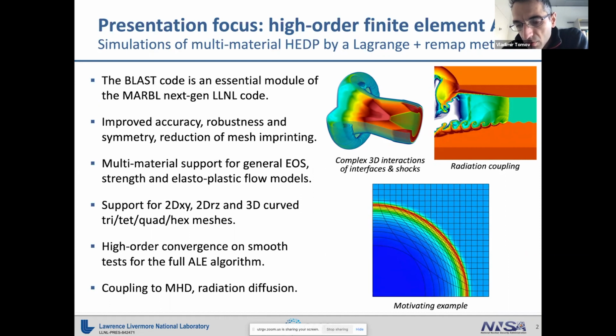So the things to observe here, first, this is a very coarse mesh. And by doing our Lagrangian method, moving mesh method, we can get a much better resolution. You can see how the mesh, in a sense, follows the motion and gets good resolution at the shock. And one cannot get this level of accuracy with the Eulerian fixed mesh method, especially on this resolution.